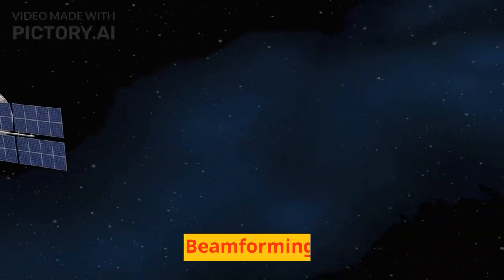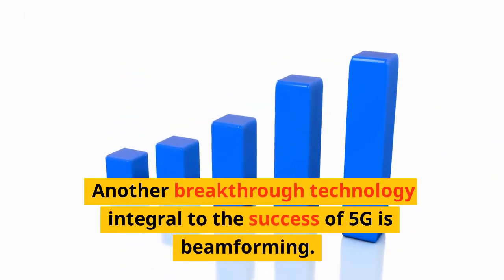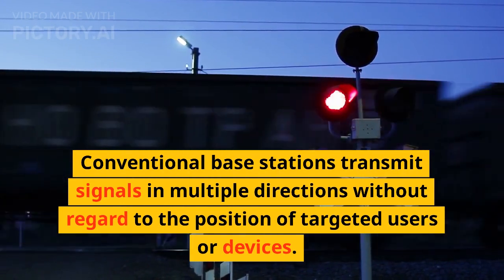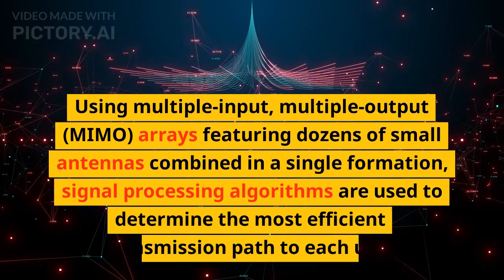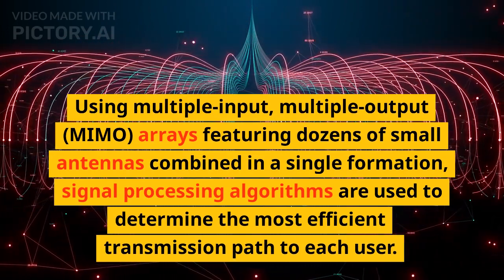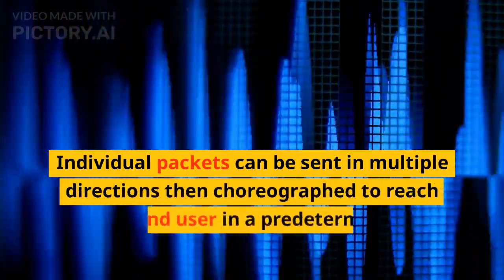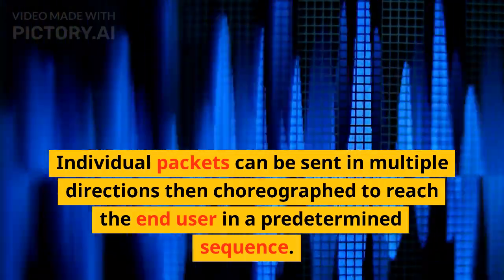Beamforming. Another breakthrough technology integral to the success of 5G is beamforming. Conventional base stations transmit signals in multiple directions without regard to the position of targeted users or devices. Using multiple input, multiple output, MIMO, arrays featuring dozens of small antennas combined in a single formation, signal processing algorithms are used to determine the most efficient transmission path to each user. Individual packets can be sent in multiple directions then choreographed to reach the end user in a predetermined sequence.